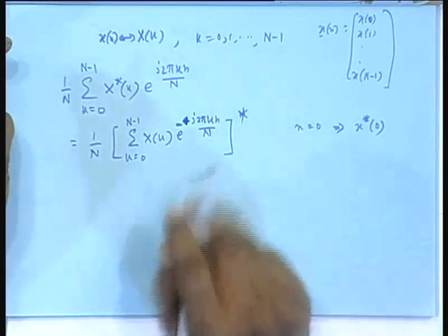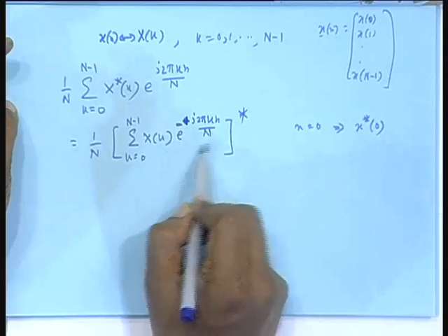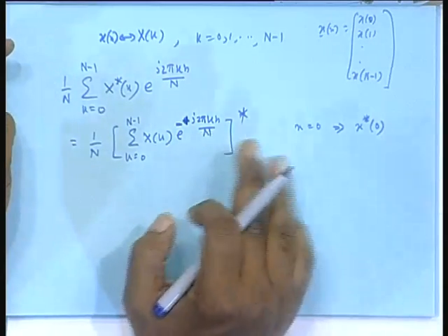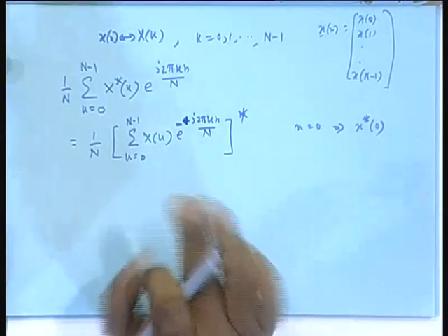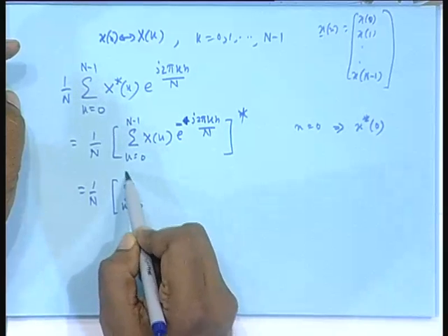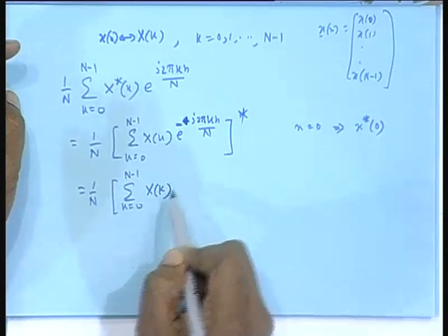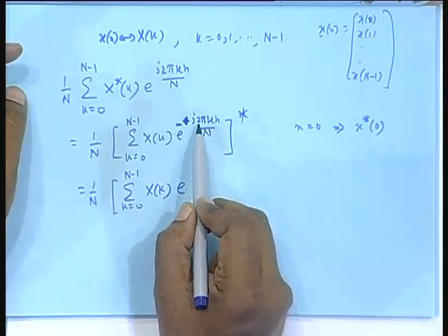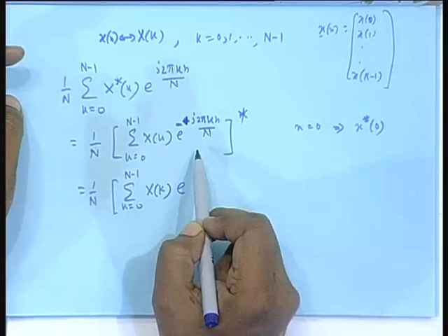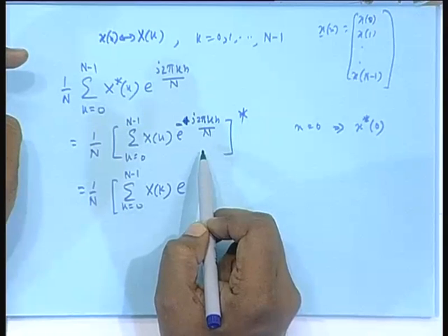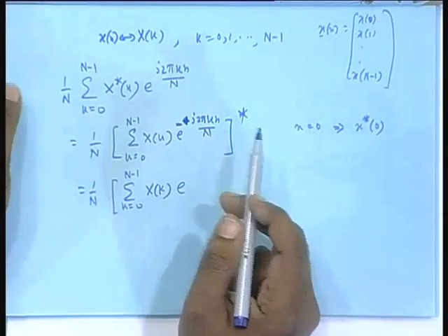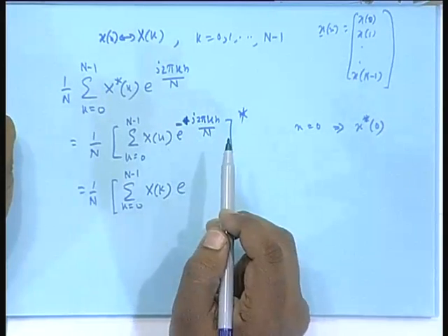and for n not equal to 0, there is a problem, because this is present with a minus sign, otherwise it becomes 1 independent of whether it is minus or plus. Now, that phenomenon goes. So, then I apply a simple trick. I add j 2 pi into capital N by capital N into k, e to the power j 2 pi into k, there is always 1, and that k I am writing as capital N by capital N into k.